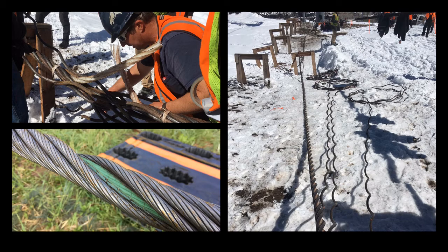First, some of the strands are unwound from the wire rope. This is shown in the image on the right, with 3 downhill strands unwound. This is done by passing the strands over and under the wire rope to make sure it does not get tangled. The image on the bottom left shows a section of wire rope with a strand missing that has been unwound for part of the splicing process.